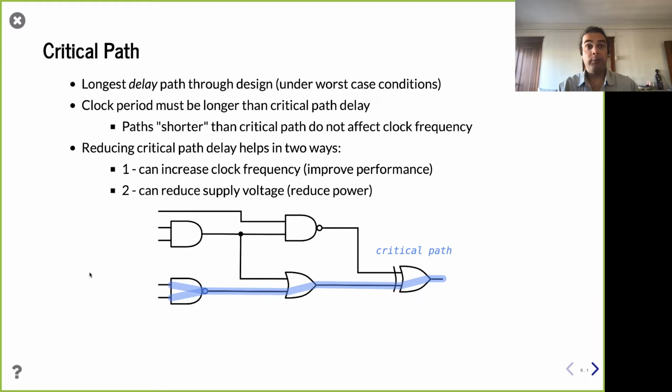And so in terms of the clock period, how it fits in, right, is, within a clock period, you need to get the results out of a register, through whatever logic you have, and into the input of the next register before the next clock period, right? If that takes too long, the register is going to see the wrong value, and you're going to have a corrupted design, right? And so it's important that the critical path delay be less than the clock period delay, right? So that way the longest path has time to settle. That is, the end of this logic path, which is being fed to a register somewhere, has time to be a perfectly stable signal before the register reaches value and moves on to the next cycle.